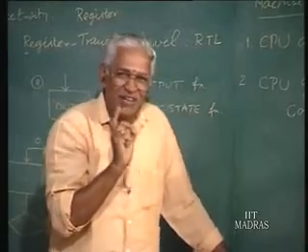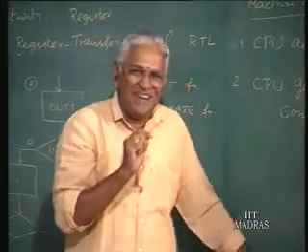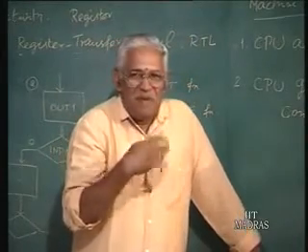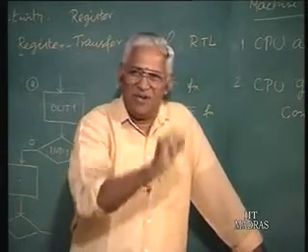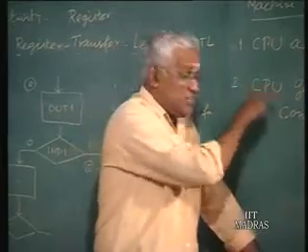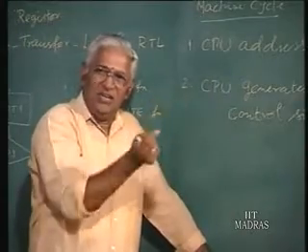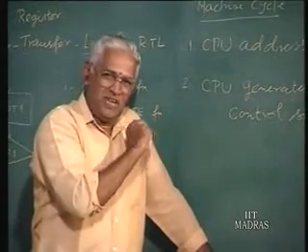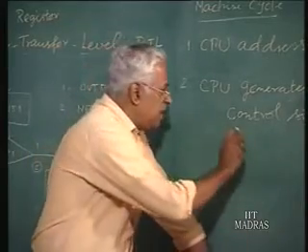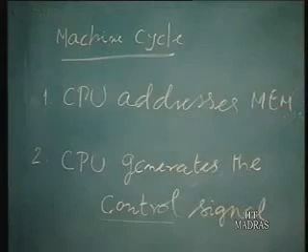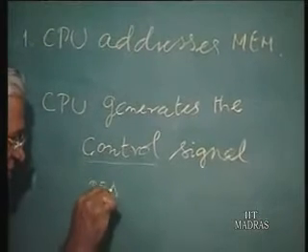Now remember, when I say data, don't confuse program instruction and data. From the memory's point of view, whatever is stored is a piece of data, some unit of data. In the instruction fetch, the memory must respond with the instruction word. That comes as data over the bus, which the CPU will read. So the appropriate control signal in the case of instruction fetch will be read.